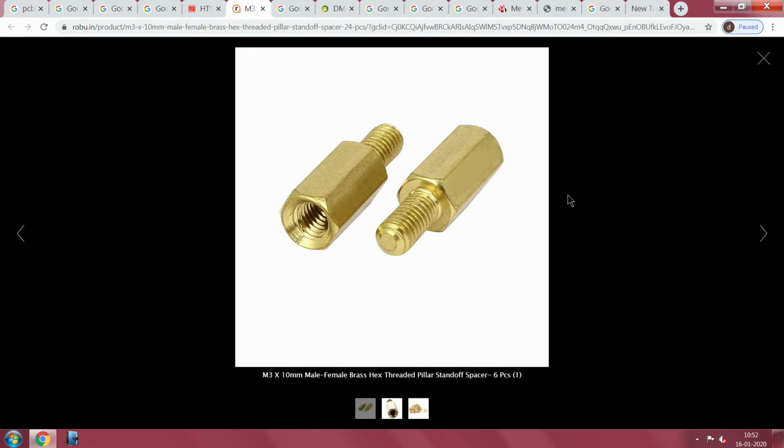Sometimes that whole stack, let us say you have two PCBs, they have ground planes, you have a ground, then two circuit inside planes, another either ground or the other live things and all that. Now, we may want to have the ground planes connected, or we want to have supplies connected. The advantage being it also leads to a small element of shielding.